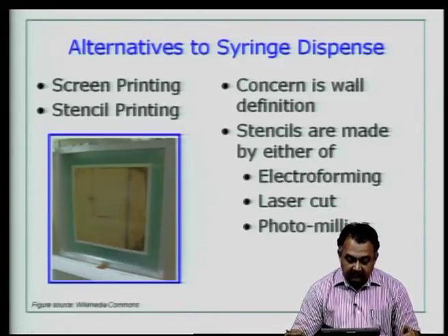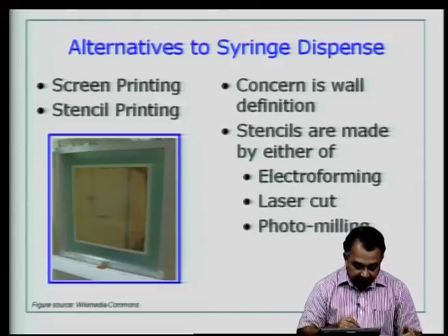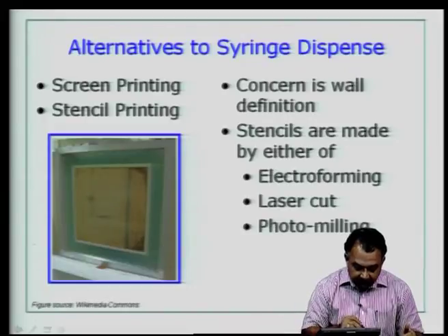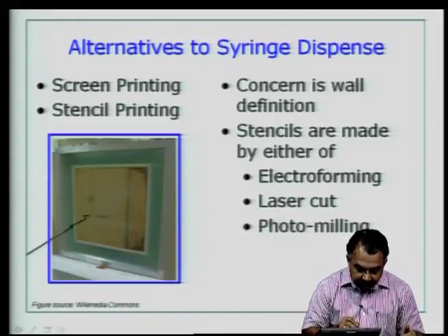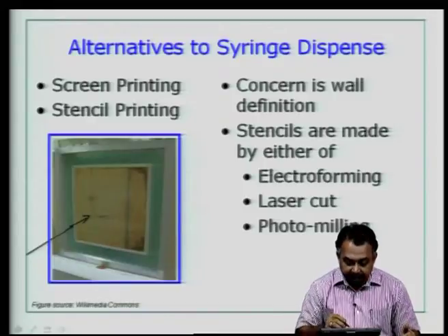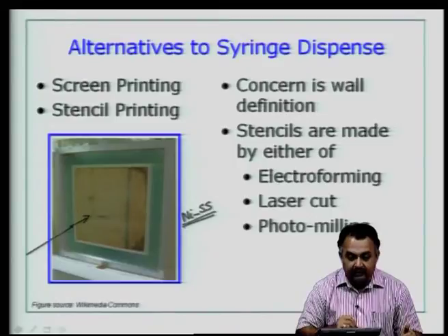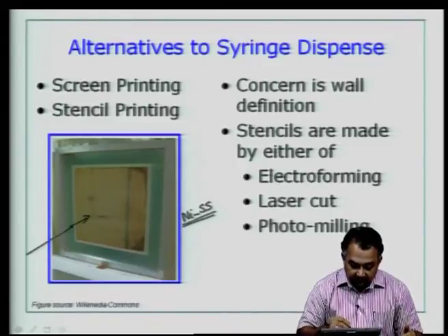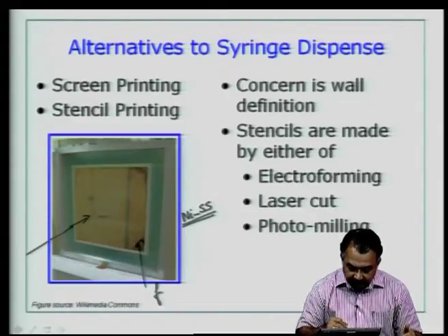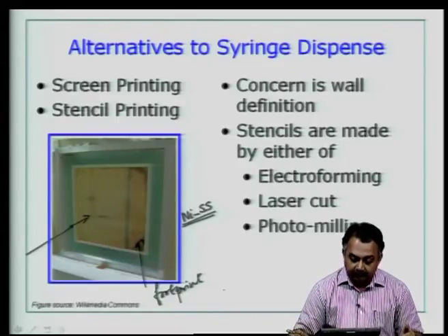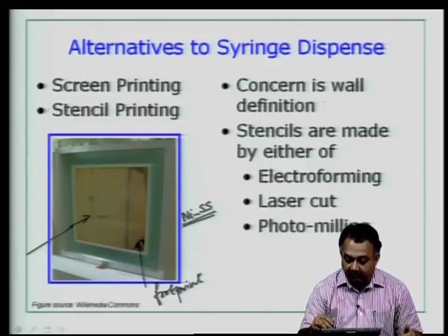The concern here is the wall definition. That means, you have to generate these kind of screens that is made out of typically nickel stainless steel, okay, very thin sheets, and then you have to generate the footprint on this. You have to generate the footprint of your SMD assembly pattern on this particular stencil. So, the concern here is the wall definition. Do you get the right